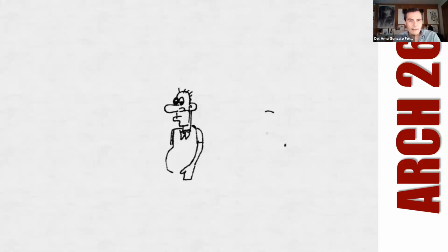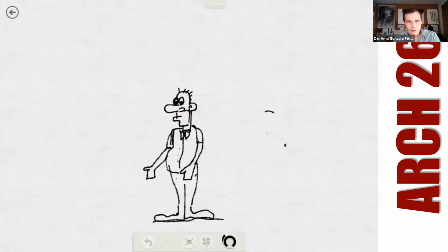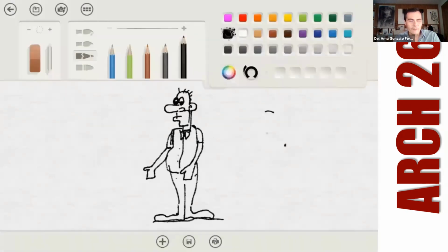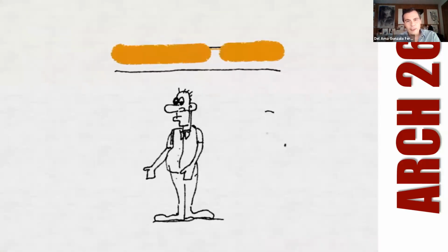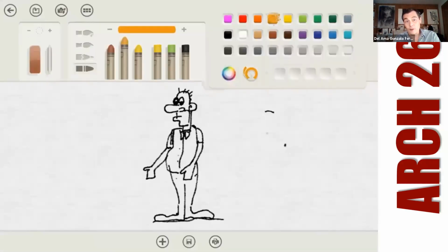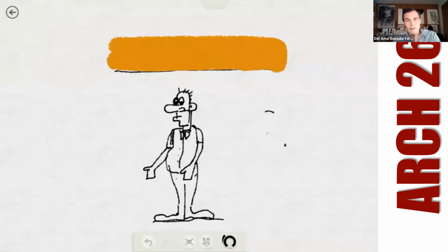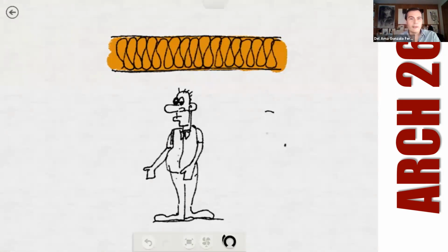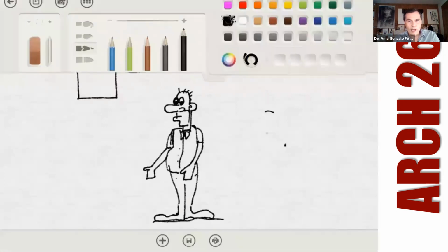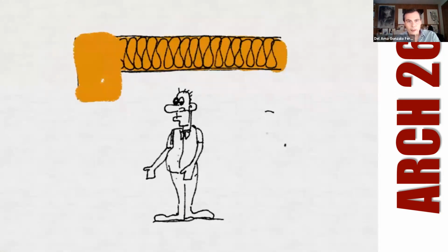Then we're going to design the envelope, and then we're going to calculate the thermal properties of that envelope. Okay, so this is the people, and finally, at least we'll have a roof. And the most important element in the building envelope for us is the thermal insulation. So we assume that we have a very thick thermal insulation. We always have this hatch for the thermal insulation, and then after the roof, we will have walls and windows.